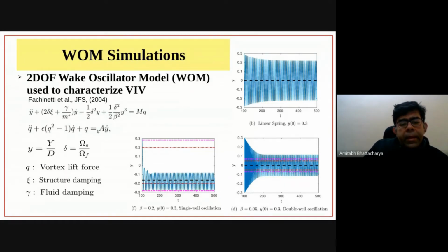There is also forcing on the right hand side from the cylinder, but you can see that even if there is no forcing because of the movement of the cylinder, this will still reach a limit cycle with the vortex shedding frequency, and with some normalized amplitude of lift force equal to 1. So these are two coupled equations that we are solving, and it's a very, very crude type of model, but you can still get a lot of insights from it.